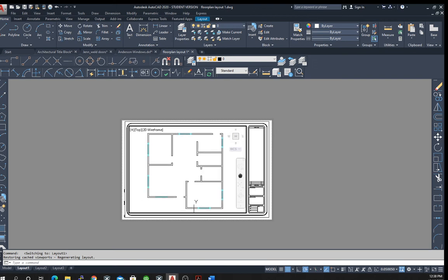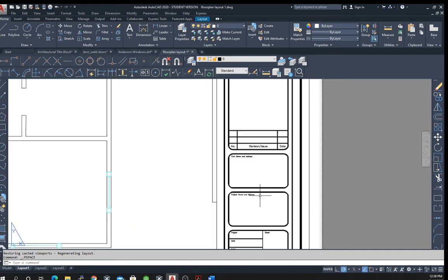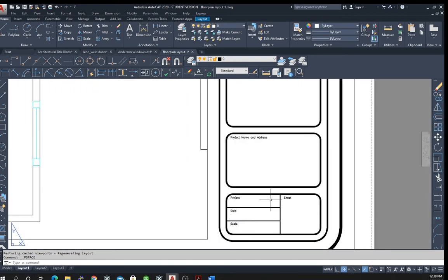you want to take one drawing and make it a drawing of your floor, first floor. You'll have to annotate this drawing, so you should come over into the text box. Enter the project, first floor, date, the scale.